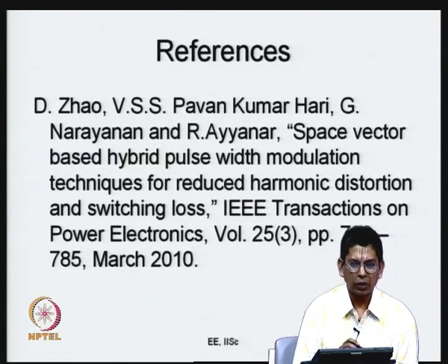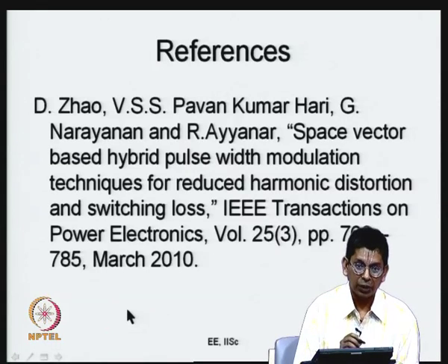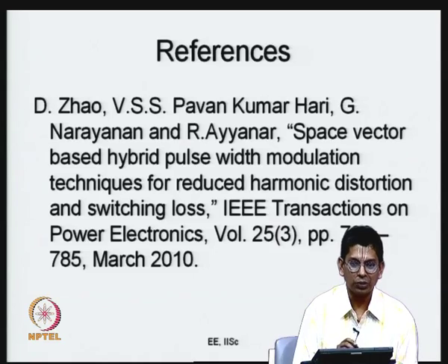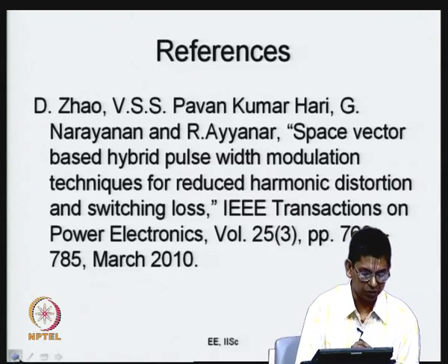You can see this continual clamping and split clamping much more easily when we deal with the problem of bus clamping PWM from the space vector domain. In the next few lectures, we will move over to the space vector domain and start looking at PWM generation from the space vector point of view. At that point it will be very clear how these two possibilities of continual clamp and split clamp are much easier to see.